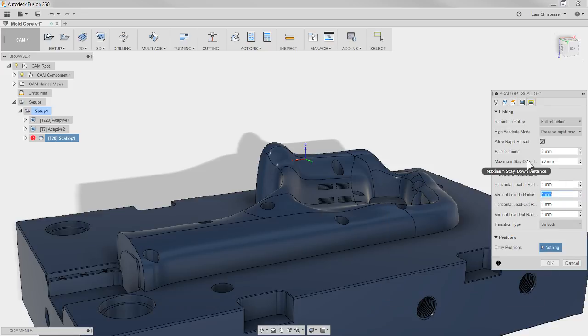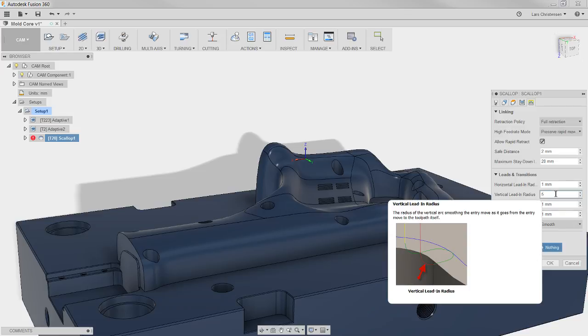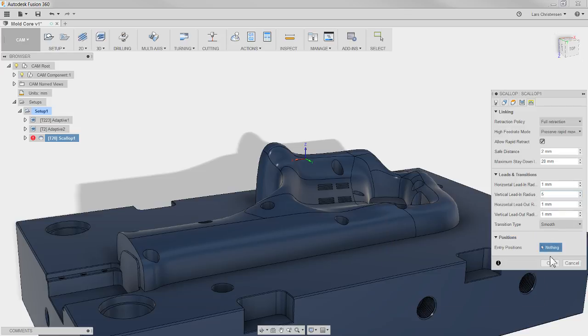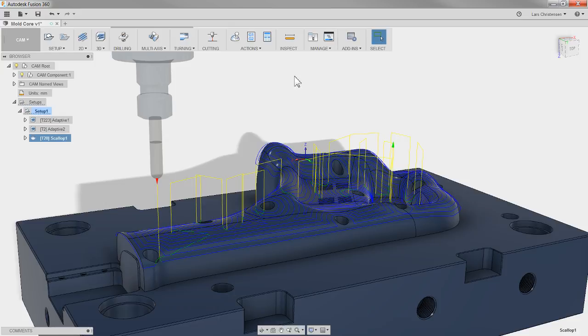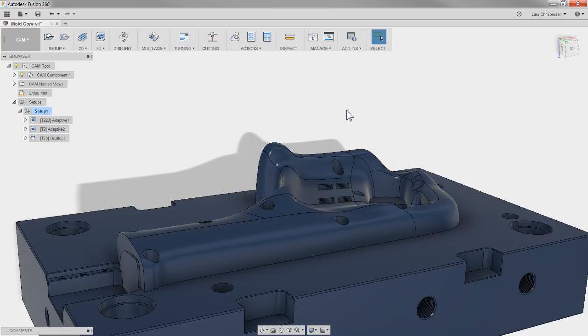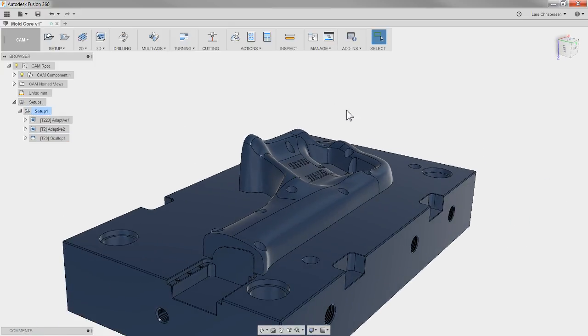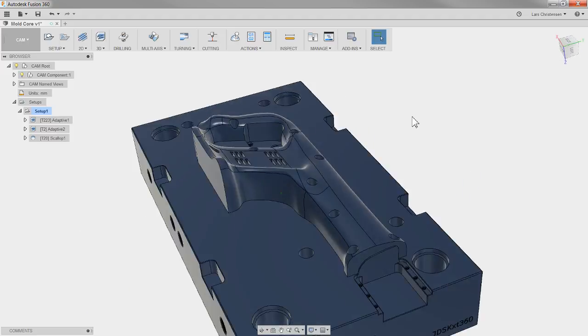If we change that, just make it a little bit bigger, because that really doesn't matter. You don't want it extremely big. But if we're changing this just to 5, that means we're going to make that lead-in radius a little bit bigger, and hit OK, then that arrow goes away. So if you ever see that one, that will wrap it up. Okay, almost done here. We're getting up on the half-an-hour mark. I'm talking too much.